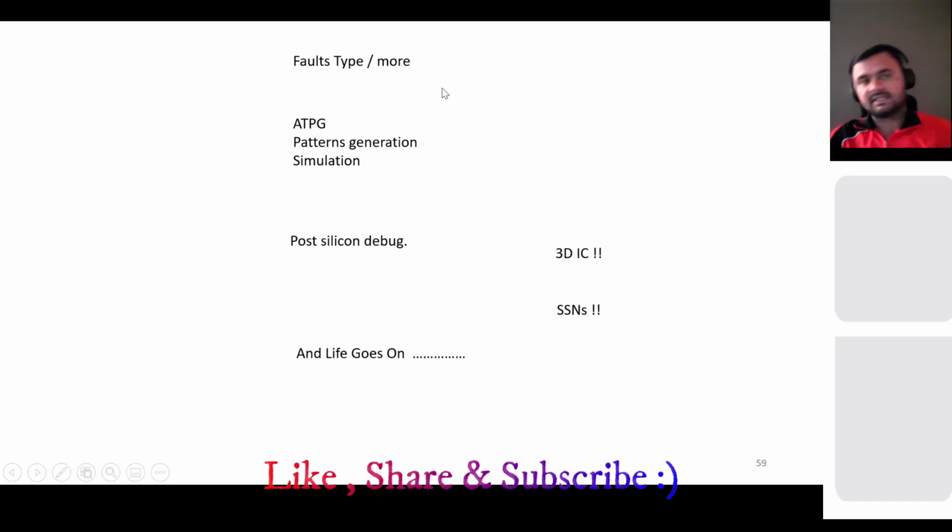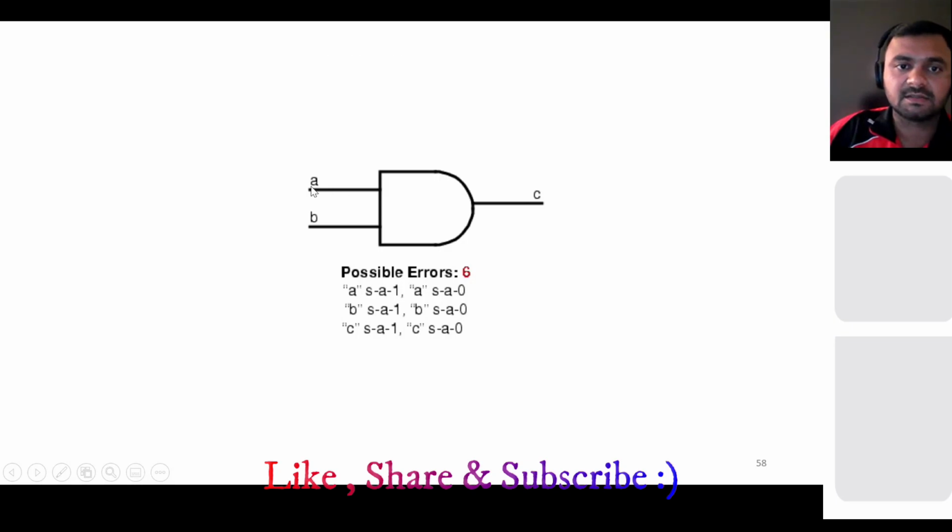Okay, now I think this is the last slide. We have different fault types. We just saw stuck faults, where a node is stuck to VDD or ground in a chip. There are many other faults, like a node that is slow to rise or slow to fall. Suppose this A is connected to clock, and the clock is slow to rise and slow to fall, meaning the rising edge and falling edge are very slow. That comes under at-speed testing, or we call it transition testing.